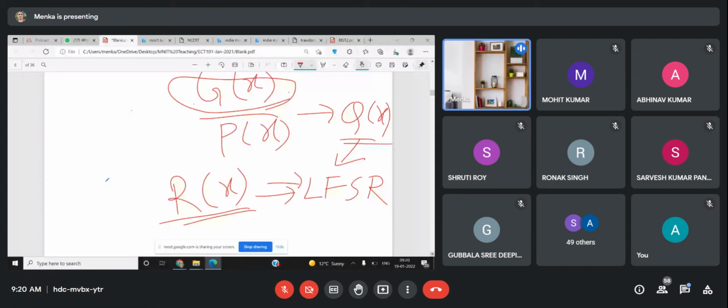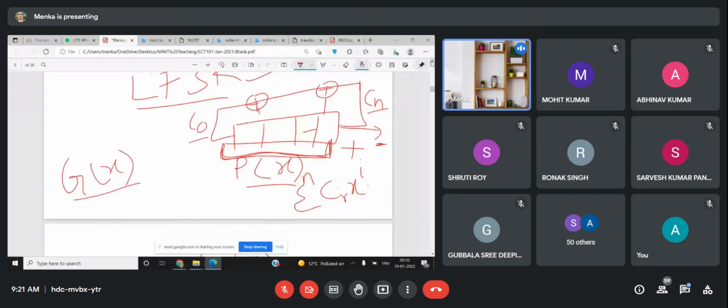So I also told you how to calculate the next set of states for the flip-flops. Wherever the XOR is there, you just calculate that, and after that calculation the updated value for the next cycle will appear. Okay, so for every clock cycle you will be calculating the new set of values.